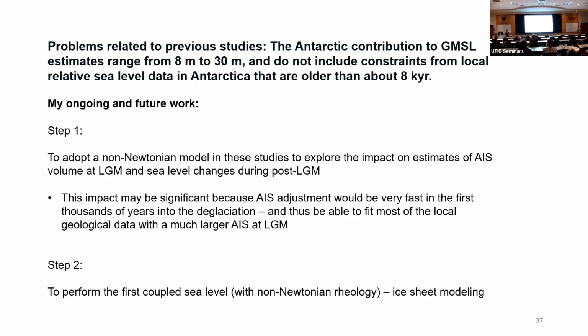When you look at your non-Newtonian rheology, what you call the transition stress, is that going from dislocation creep to diffusion creep? Yeah, the transition stress is defined as where the dislocation creep and the diffusion creep contribute equally to the total strain rate. So it's like a threshold between the linear and the non-linear.